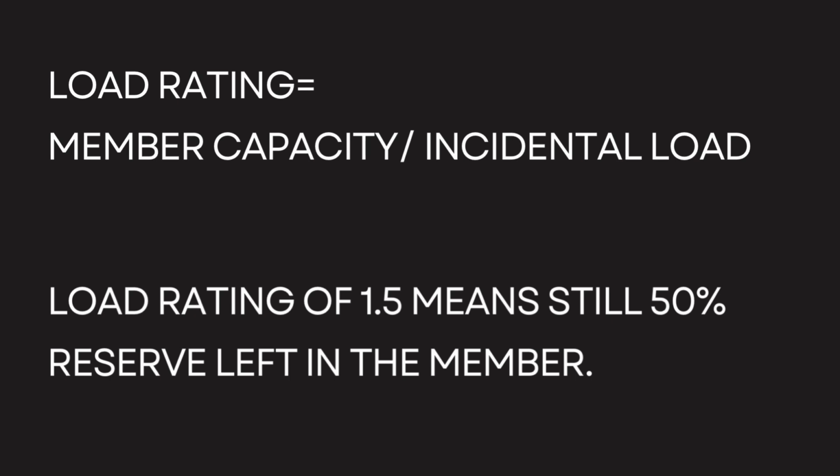This concept is very popular in USA, Europe, etc., but can be used in India also, as it gives idea about how much extra load the bridge can take without need for testing again, if load is to be enhanced again. In this method, instrumentation with present loading test train is used to validate the numerical model and then projected to see what maximum load generates the permissible stresses, strains, or deflection, etc. And load rating of particular members and load rating of overall bridge is worked out. In some cases, the enhanced load is once again run to validate the previous conclusions.